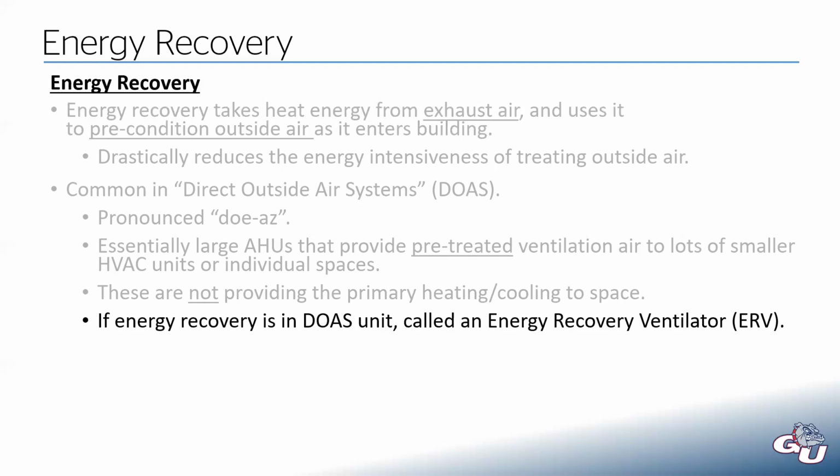You still could, but if you had a 10,000 CFM DOAS unit, then that would have a very large benefit to having energy recovery. And actually, by code, you might have to provide that. They would make you put it on there just because it makes so much sense and would save so much energy.